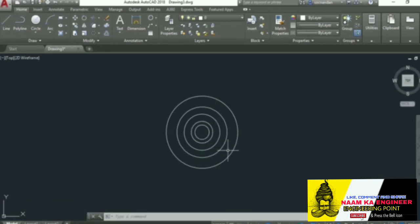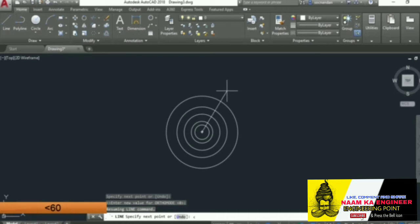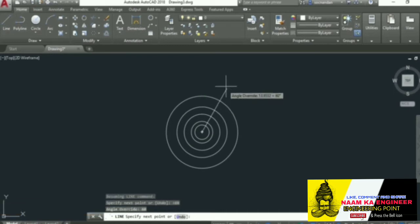We will now add details to the drawing, and for that we need to first make a line. So go to this line tool and click on the center, and now make a line inclined to an angle of 60 degrees. So type this angle sign, then type 60 and press enter. And here we have it, the line inclined to an angle of 60 degrees. Now click anywhere outside the last circle and make a mirror image of this line. So select this line, go to the mirror tool, click on the center and click vertically upwards and then press enter. And here we have it, the mirror image.